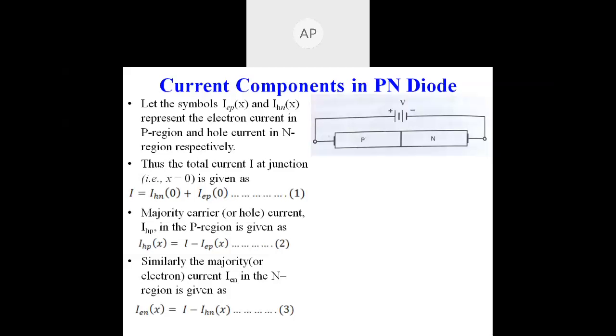This is the barrier potential developed across the junction. So these minority carriers diffuse away from the junction exponentially with distance, as shown this way. Now let's consider that their concentration falls steadily due to recombination with the electrons and the holes respectively. Since the diffusion current due to the